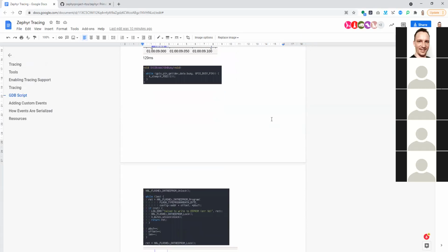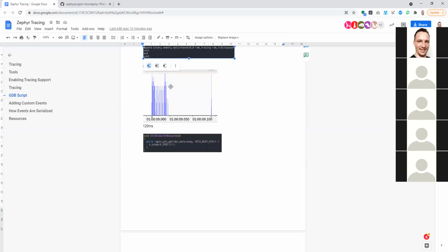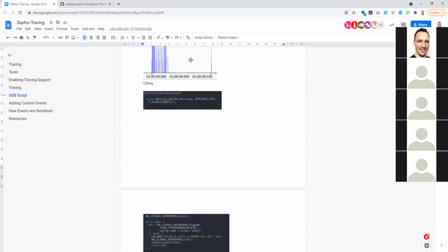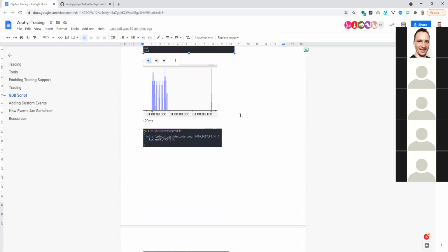The pause is generated because during this time, the application is writing into the internal EEPROM of the chip. And this process takes a very long time. It actually takes a long time to write to the internal EEPROM. And this code ends up consuming a lot of CPU power here. So we can discover things like this, and we can see how we can optimize the application. For example, if in this case we wanted to optimize for power use, for how much power the application is using, we can optimize things like this.